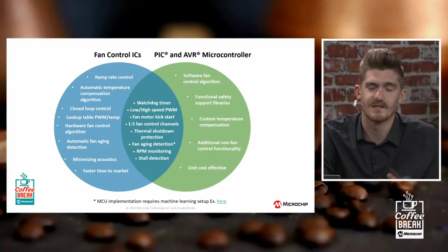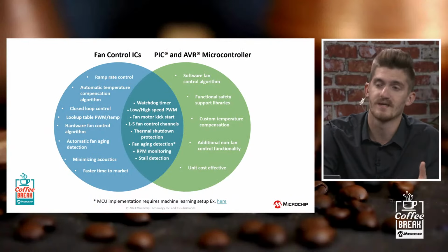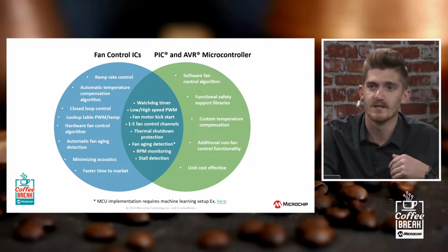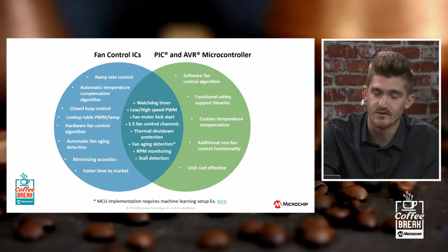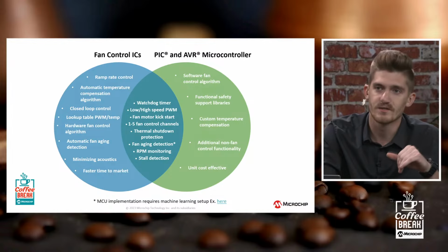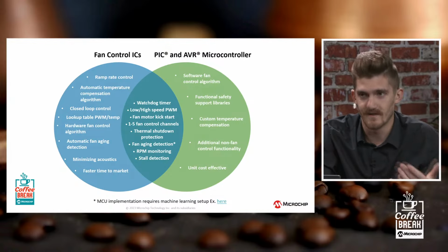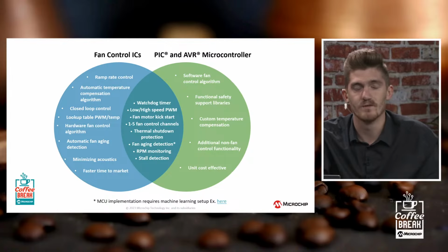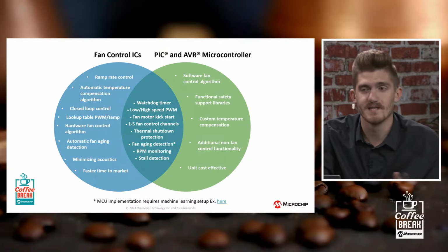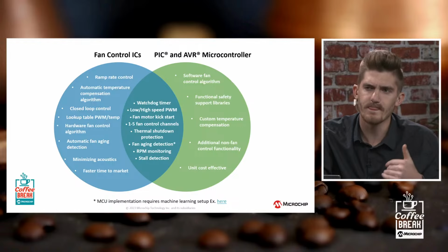Yeah, so for the fan control ICs versus a microcontroller, it's all about picking the right tool for the job for your application, depending on what challenge you have, like we presented on the previous slide, depending on what's important to you. So from a microcontroller perspective, it's just a little different paradigm. We have these core independent peripherals that can drive the fans, but then you just have a general purpose CPU controlling all of them. So you're going to have to do some software development in the beginning of your application, which you wouldn't have to do with the ICs. Right. But the pro to that is then you get a lot more flexibility and customization.